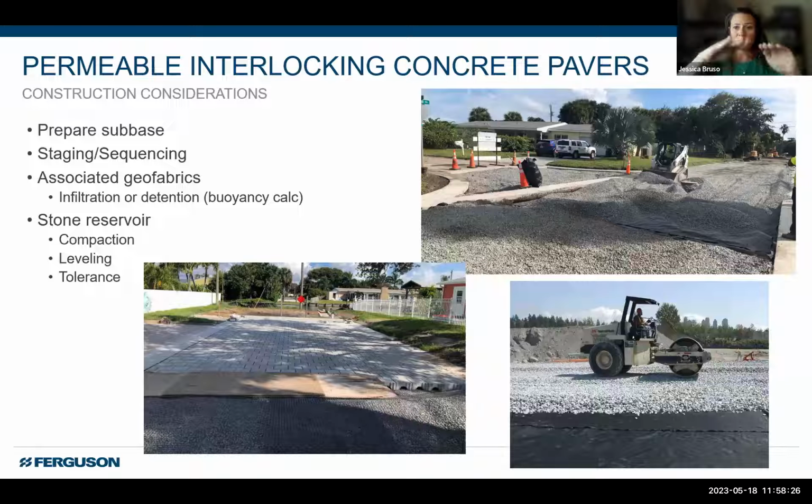So you don't have one paver here and one paver here, and this really big difference. But it is very specific on the different types of pavers, what that tolerance should be. It's usually like 3/8 of an inch, is very, very minimal.